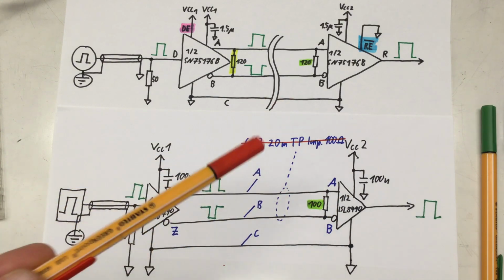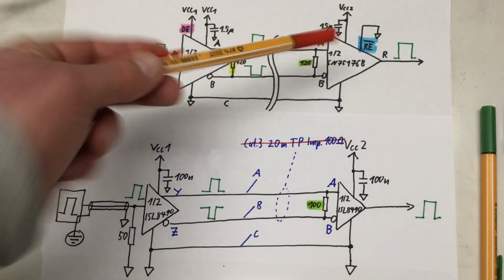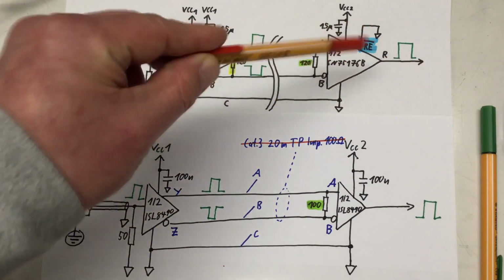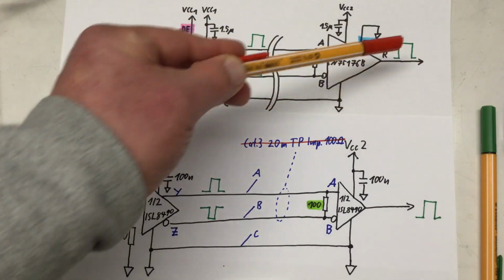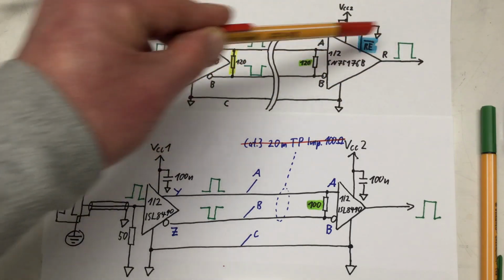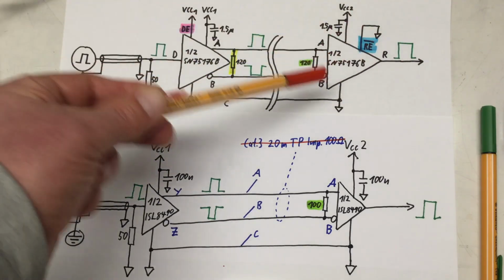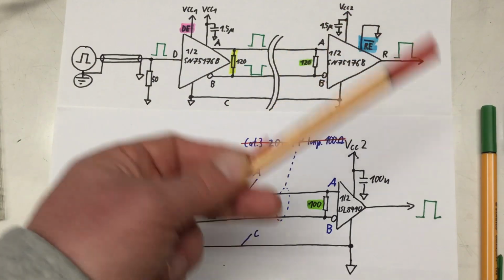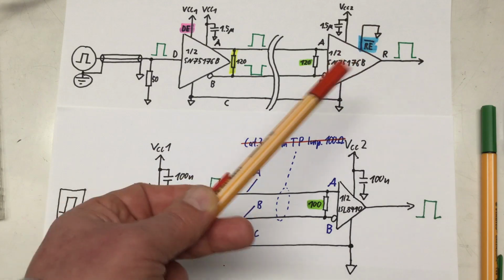We will see why in a second. Third, the output of an RS-485 transceiver can be disabled, that is set to high Z, using that not read enable pin. But that's really just a convenience thing for writing software for RS-485.